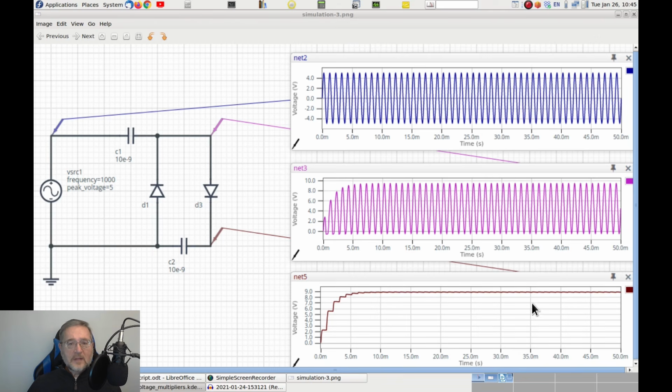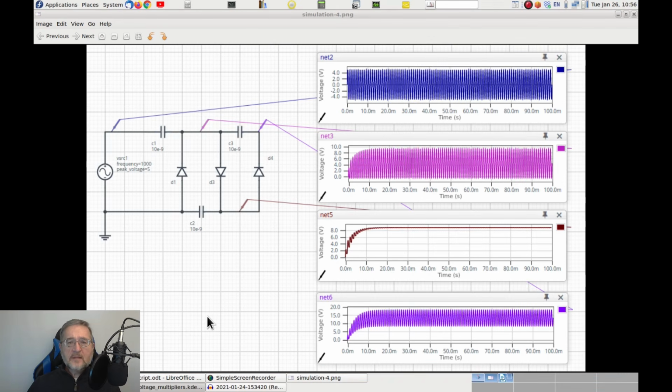And, like we did with the DC-DC multiplier, we can keep adding stages to this AC-DC multiplier to obtain higher and higher voltages. Here is what happens adding one more pair of diode and capacitor. This new stage is powered by the voltage present at the output of C1, which is still a sine wave but shifted toward the positive. Because the input of this last stage is a sine wave, it will work like the very first stage and will produce a voltage like the one in diagram 4. Basically, we have created another sine wave even more shifted toward the positive.